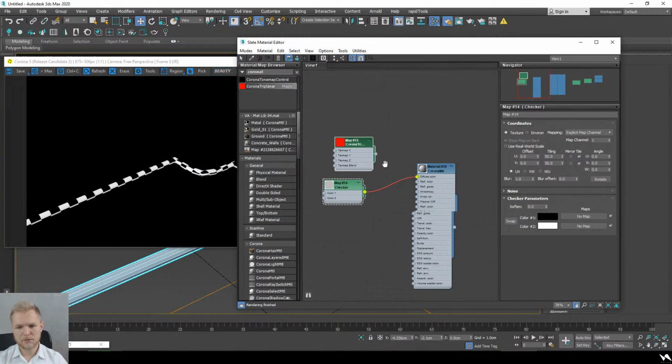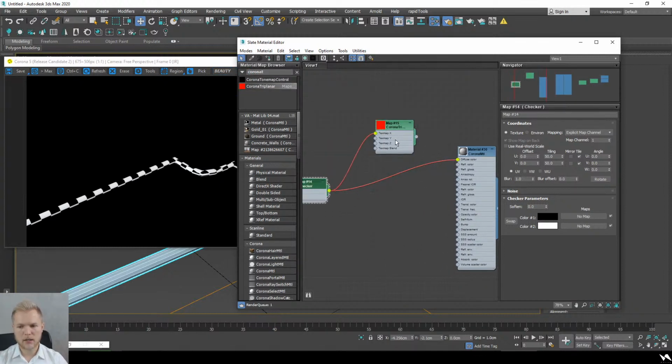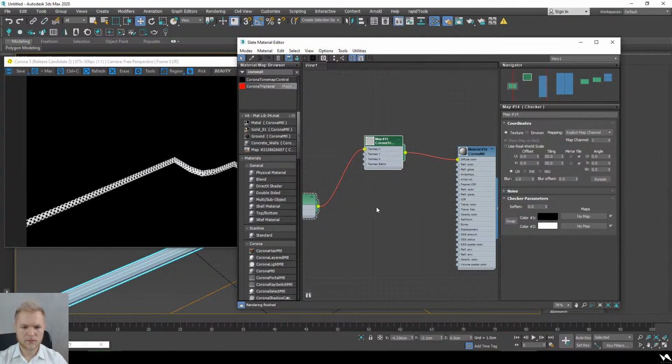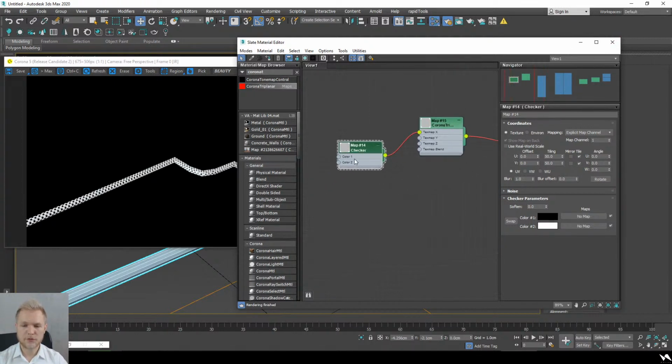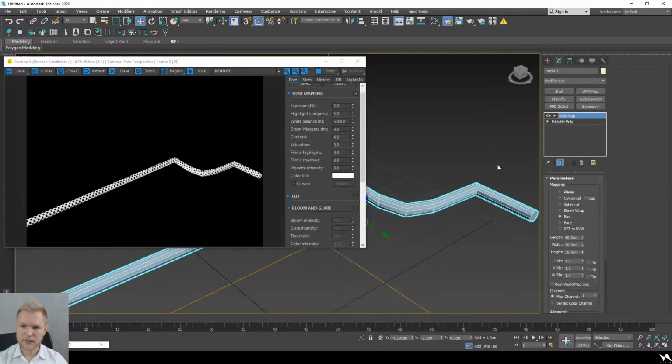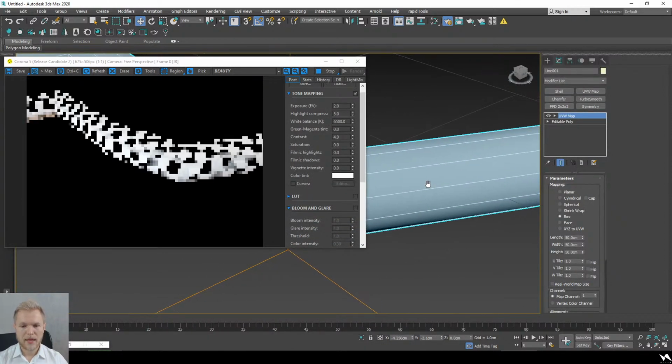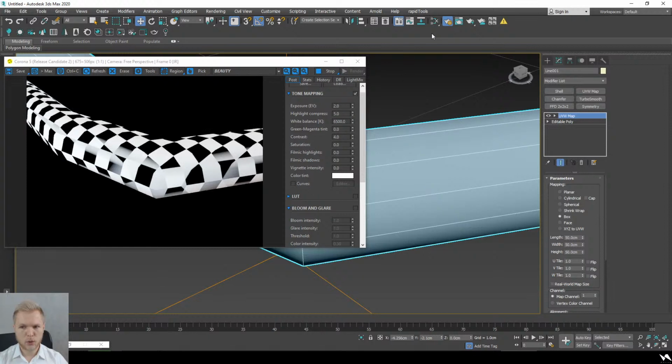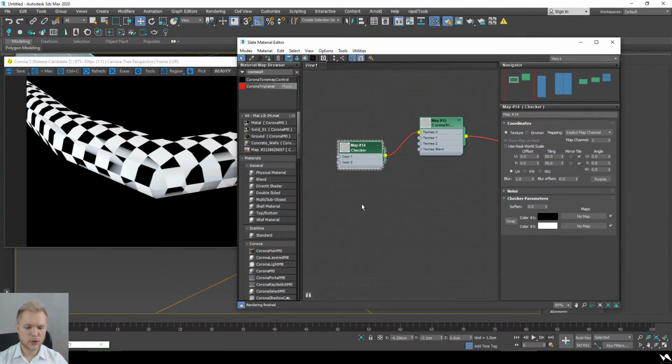Remember, with objects that require a lot of detail when it comes to mapping, we will have to resort to UVW unwrap. But why should you use Corona 3-planar map? This is the reason. It tries to blend all of your maps so that we have no transition problem.